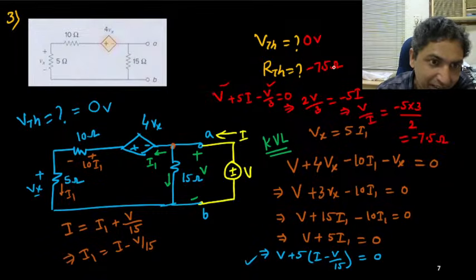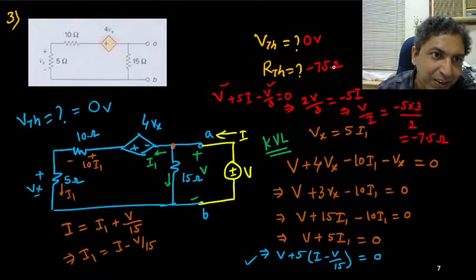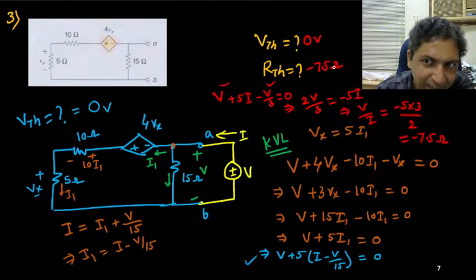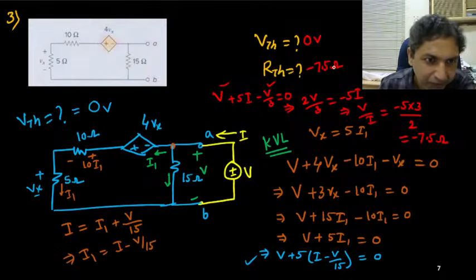That I am stressing, just giving you that in this example we have got minus 7.5. But you can see that in our previous example it was positive. In this example it is negative, but in the previous example it was positive. So you may get positive or negative resistance, but negative resistance implies that the circuit will surely contain some dependent sources. Okay.